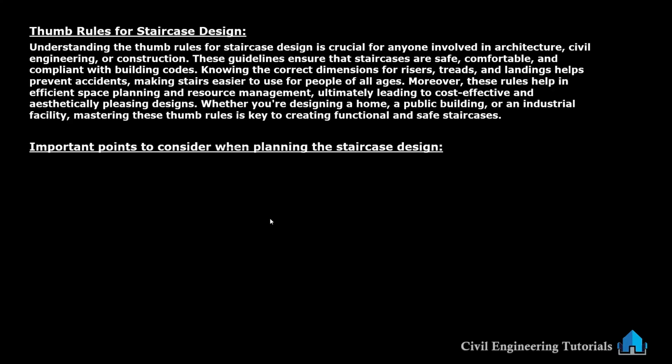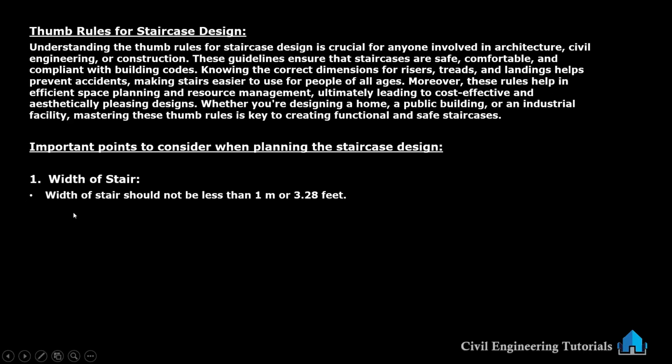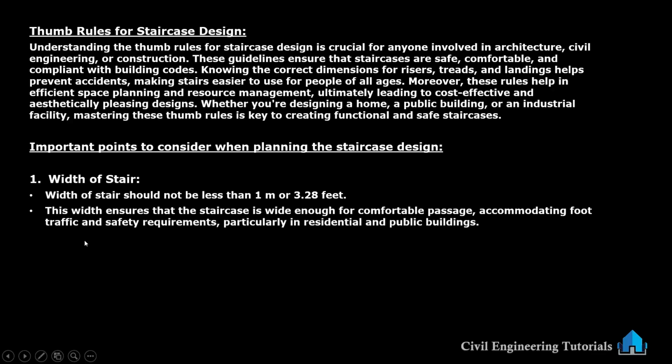First, important points to consider when planning the staircase design. Width of stair. Width of stairs should not be less than 1 meter or 3.28 feet. This width ensures that the staircase is wide enough for comfortable passage, accommodating foot traffic and safety requirements, particularly in residential and public buildings.